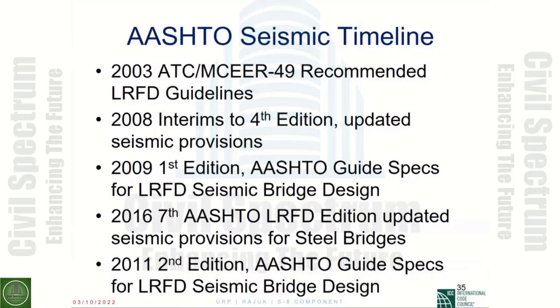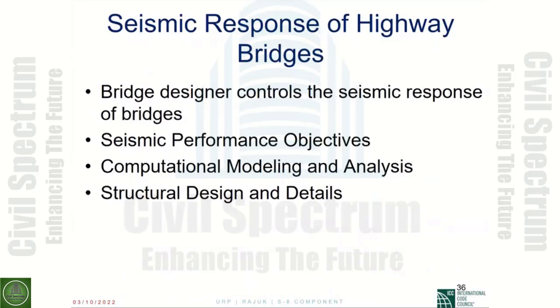We have implied details for the reinforcement, for the support length, and for the confinement, so that we will be able to provide the level of ductility you need. So the basic answer is that if you design the bridge based on the main specs, which is force-based, or based on the guide specs, which is displacement-based, you will get the same performance. You are the designer and you really control the seismic response of the bridge. You need to understand that.